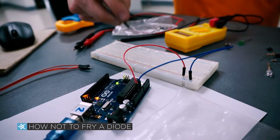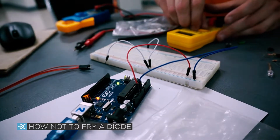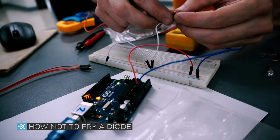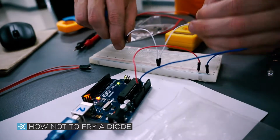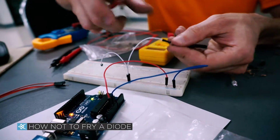So what I'm going to do here is test that I actually have 5 volts coming out of this. I'm pretty sure I do. So I'm testing between those two rails, what is the voltage, and I should get about 5 volts. I put them the reverse way around, so I'm reading minus 5 volts. I actually put my negative on their positive.